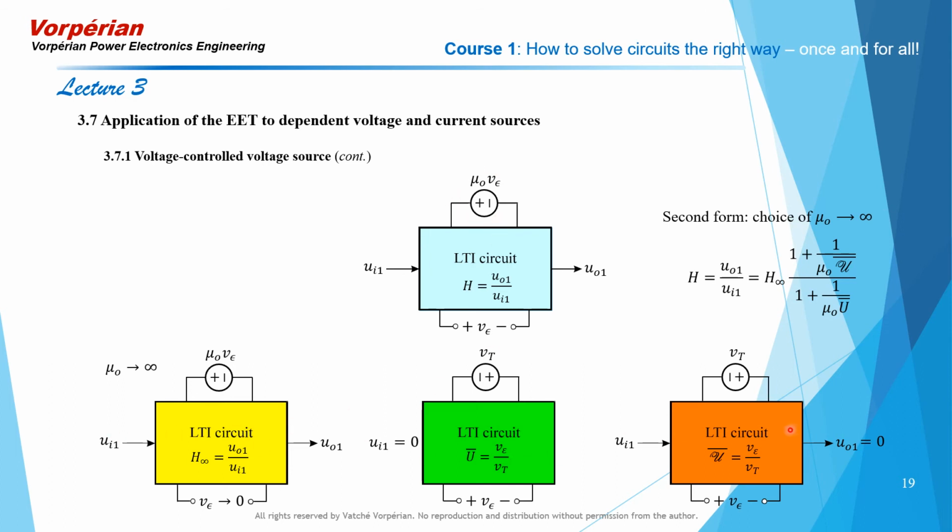By doing that, we calculate H infinity, the null inverse gain, and the ordinary inverse gain. So first you compute the transfer function with this element taken out as infinity, and then you reinstate mu 0 with the help of these 2 additional computations and the use of this extra element theorem formula.